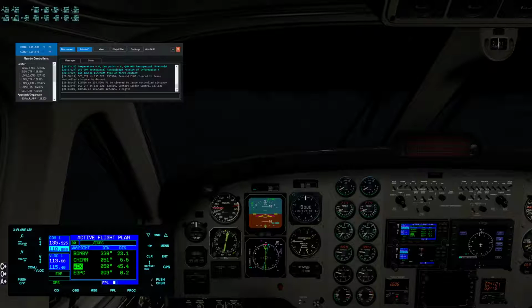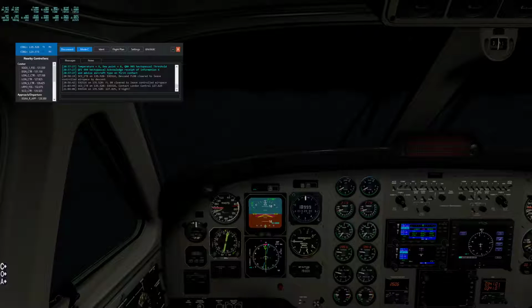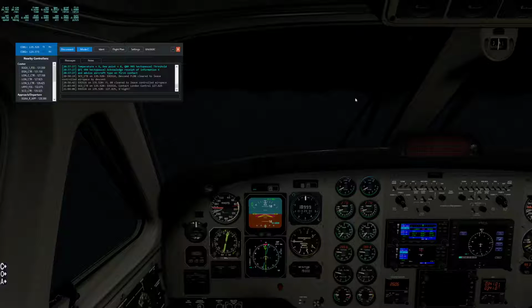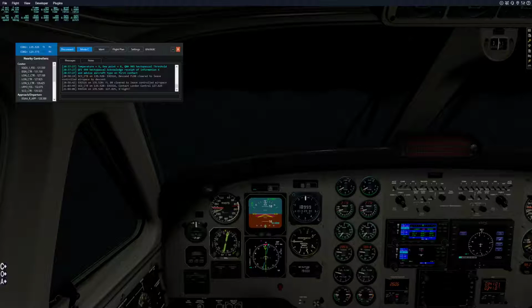If we're still flying on navigation and waypoints on the GPS display, when it says the next leg is to Chin, I know that I need to start when there's 9 miles left to Chin. But also, on the right, the DME is now reading 99.7, so it's just gone under 100 miles. So the other way I can know when to start my descent is when the DME readout reaches 60 nautical miles from Wick VOR, and that's when I would need to start descending.